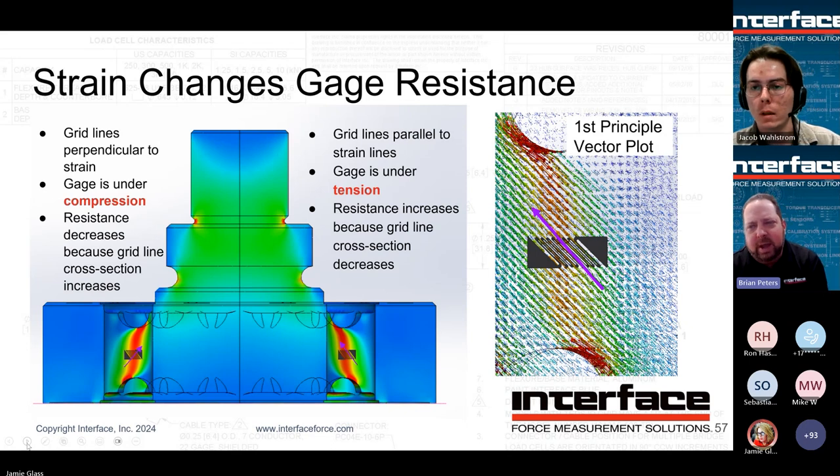We'll place the gauges in a manner that if there is by any chance a side load introduced, a bending moment, the various legs will self-cancel. So it will not manifest as a change in axial force measurement. Not only is the low profile design radially symmetric, which lends itself well to handling any non-axial load, we use 8 strain gauges, and then we do another step further called moment compensation, which we'll touch on. I just want to highlight that. Through the design of the flexure, the placement of the gauges and the types of gauges used, we can make these sensors very robust to reject anything other than measuring the actual axial force.